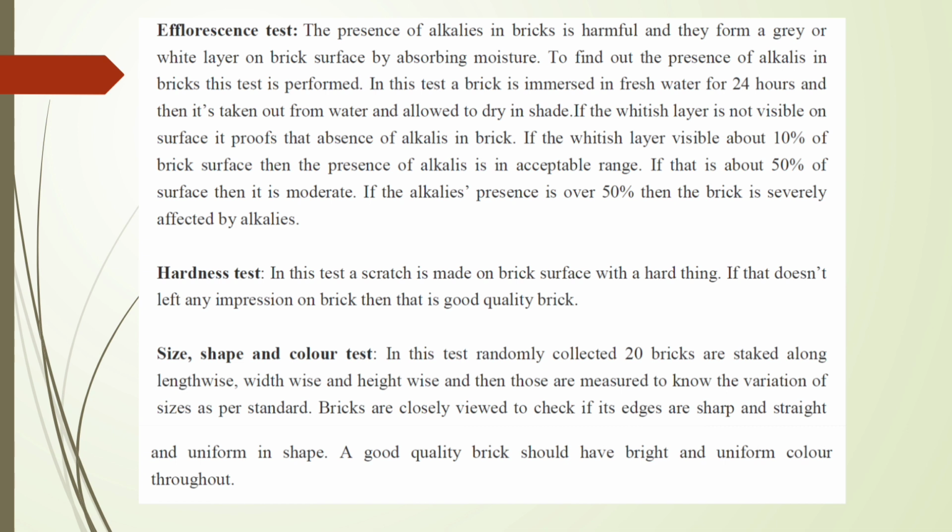In this test, a brick is immersed in fresh water for 24 hours and then it's taken out from water and allowed to dry in shade. If the whitish layer is not visible on surface, it proves the absence of alkalis in brick.